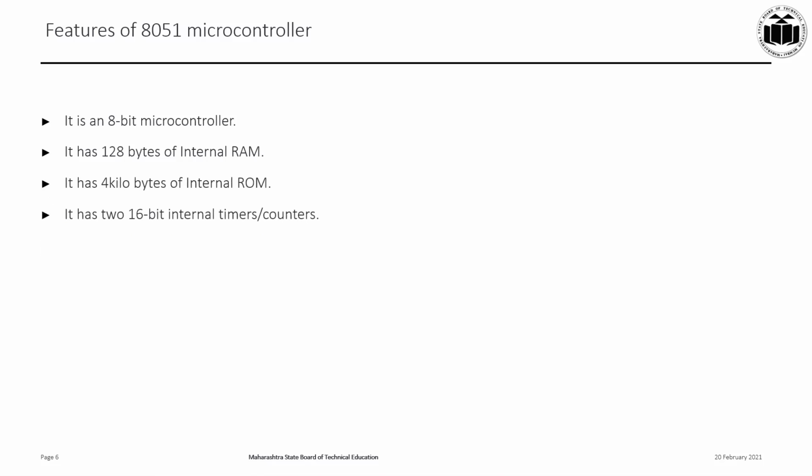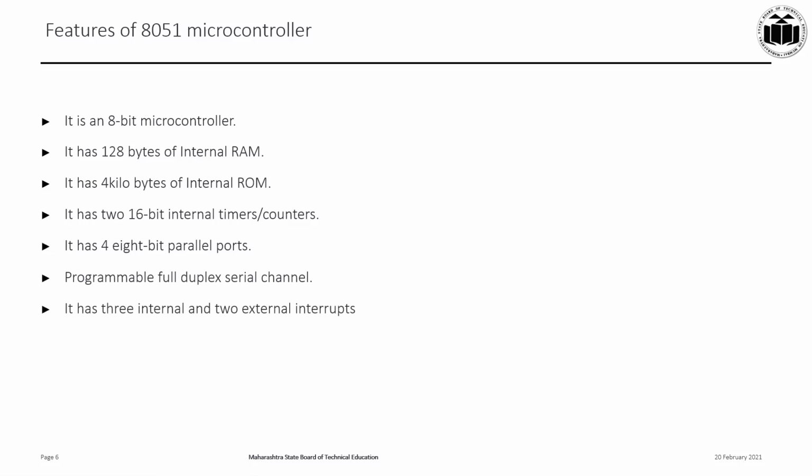There are two 16-bit internal timers or counters available. It has got 4 parallel ports and each port is of 8-bit. So in all there are 32 input-output pins available. There is a programmable full duplex serial channel. And finally it has 3 internal and 2 external interrupts.